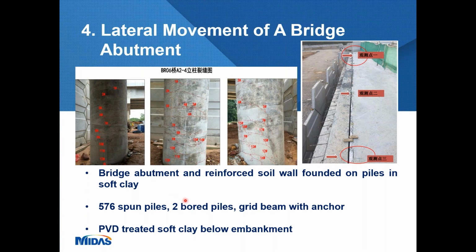This model includes a bridge abutment and reinforced soil wall which was founded on piles in soft clay. There are groups of spun piles, two board piles, grid beams with anchors, and below the embankment is soft clay. The soft clay was treated by PVD.